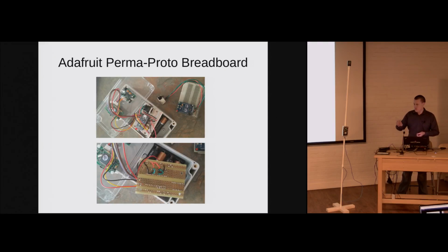And then that allows me to have the microcontroller send a signal over that wire, which Ethernet's nice because it also adds an additional layer of shielding. It's twisted pair. So if this thing's going to be going up 20, 40 feet, I don't think USB would have cut that. So Ethernet gives me that shielding benefit, which was nice. And like I said, this is running off of 4 AA batteries in the box.